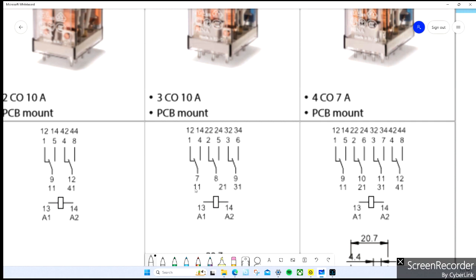It's easy for me because the first number tells me, okay, 1, this is my first set of contacts. 21, okay, the 2, that's my second set. 31, this is my third set, right? Because we got multiple sets on here. And if you're doing a diagram that you're using all 3 sets, well, what set am I attaching my wires to, right? So I like to use these ones, but is there anything wrong with saying 7, 8, 9? No, right? It's the same thing.